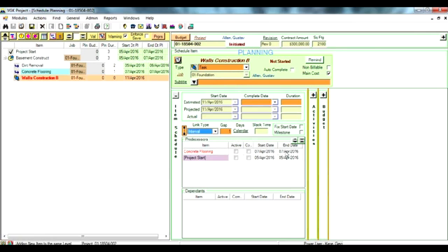Note that the flooring was done on April the 7th, with 1 day's rest means April the 8th. 2 days are added as it happens to be the weekend, meaning the 11th is our next working day, so the concrete will have a good rest. So for walls construction, we'll add 4 days to the duration, and our item has been added to the schedule.